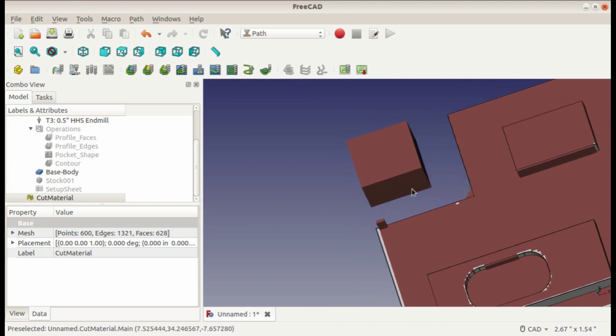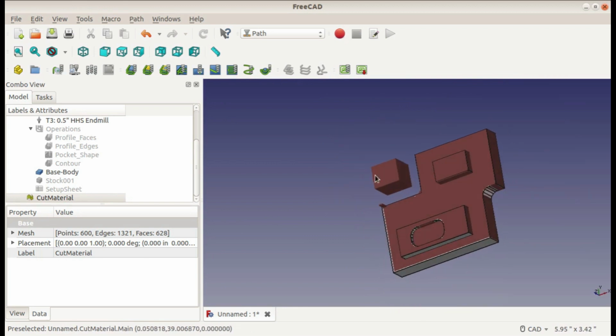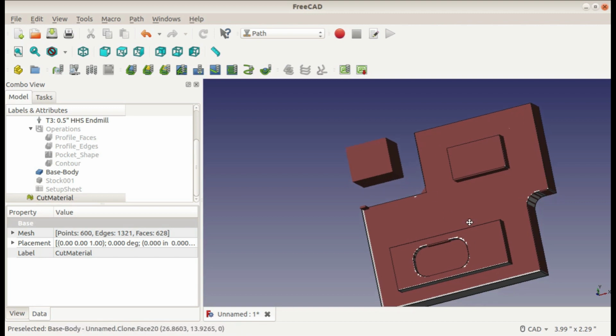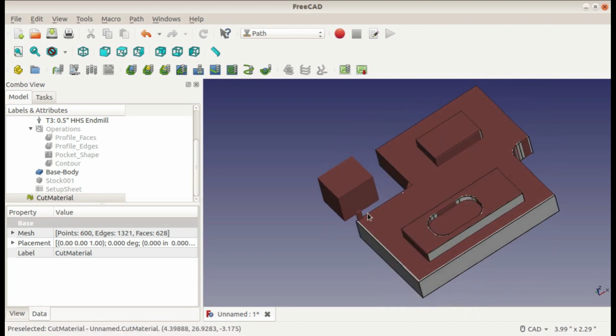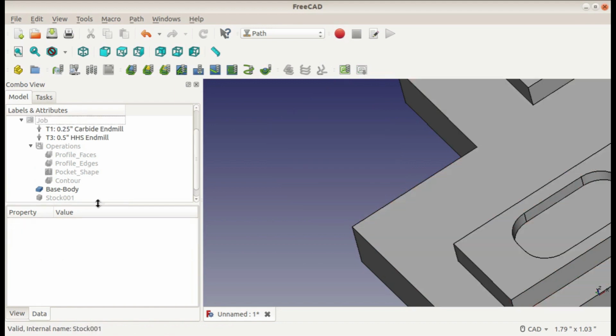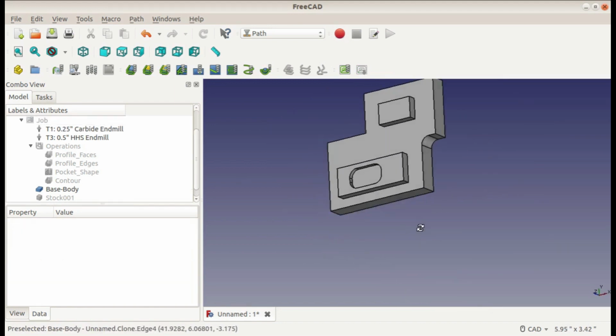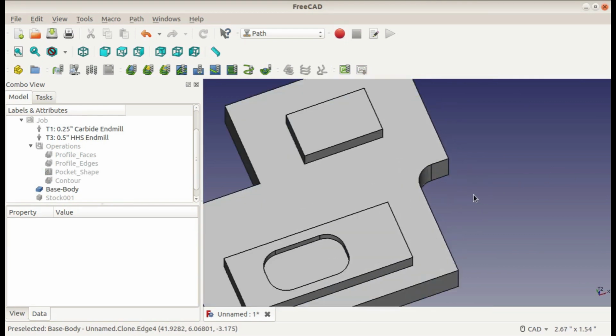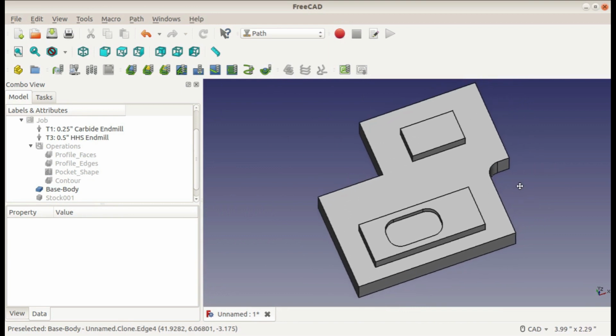And also it's nice to see what stock you have left over, so it shows us that we have this little bit of scrap. If you're running multiple parts, you might be able to try to minimize the scrap that you're creating, or maybe if you have a small part you can run right here. It'll save you time and material. So this simulate's pretty useful for those kinds of things, but I'll just delete it. I can see that of course there would be some changes that I need to make to this if I were actually going to try to run it on a CNC machine.